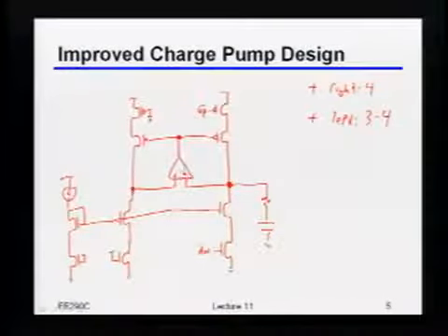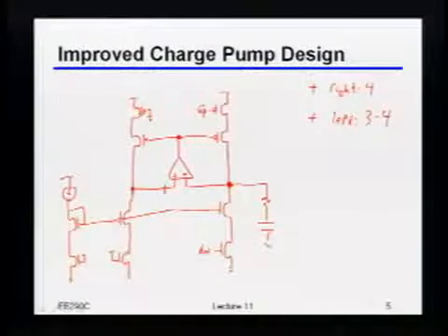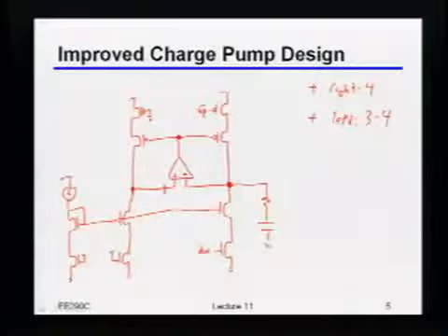So you just have to make sure that the op-amp has a high enough gain bandwidth relative to the bandwidth of the loop itself. That bandwidth of the loop is limited by your reference frequency, and compared to what you can do with the circuitry, it's not too hard to achieve. But you can't obviously ignore it. You have to make sure that the feedback loop really is stable. So it need not be very high bandwidth.